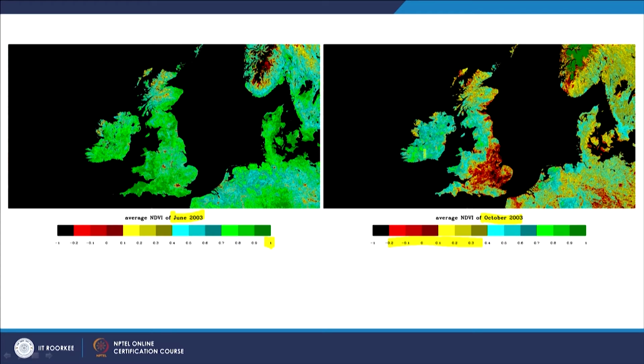So, these values keep changing from season to season. And if not season, then in a forest cover area, if some areas are showing less NDVI value, it might be because the vegetation is under stress, maybe because of some ailment, some attack by bacteria or whatever, and that may destroy the vegetation, or maybe lack of water. Sometimes in hilly terrain, if a slope is moving very slowly, then the vegetation also gets dry, and that can also be picked up through this NDVI analysis, and we can demarcate the area, but after the field verification.